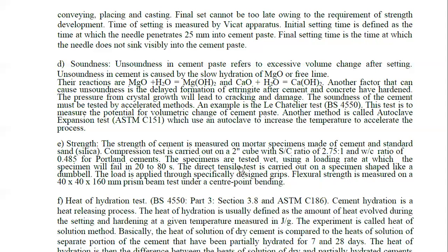The direct tensile test is carried out on a specimen shaped like a dumbbell. The load is applied through specially designed grips. Flexural strength is measured on the 40 by 40 by 160 prism beam test under a center point load bending. तो कंक्रीट की तरह ही इसका भी आप flexural test कर सकते हैं single point load के through.